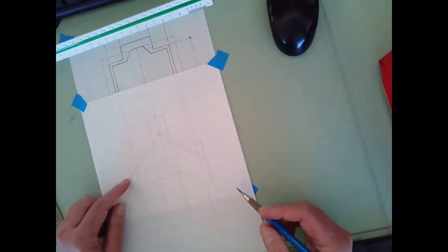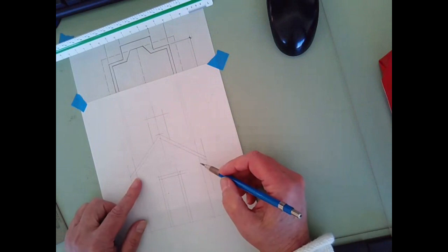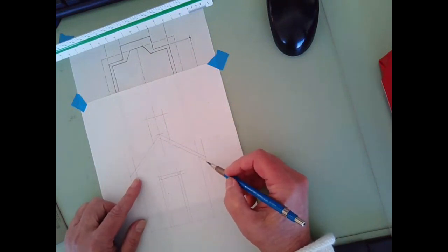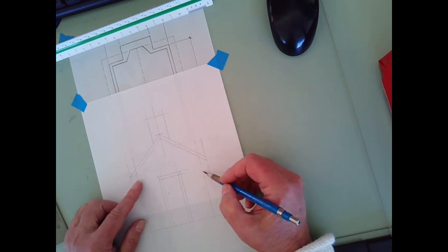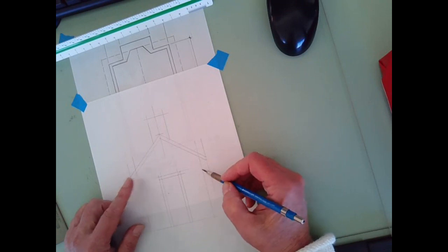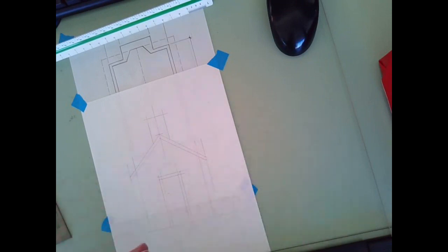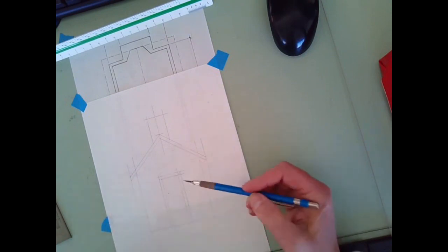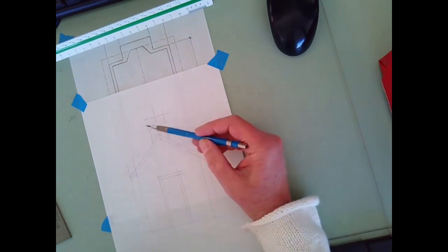So Leona, what did you say would be heavy, the roof or the walls? If I were doing this, I would say the roof would be the closest thing to me, so it should be the heaviest, and then the walls should be maybe medium. Yeah, you are correct, but I would do them both heavy because they're so close together. And we use line weights just like we did in the cube to distinguish how far things are away from us. It just gives us a visual clue in addition to the drawings.